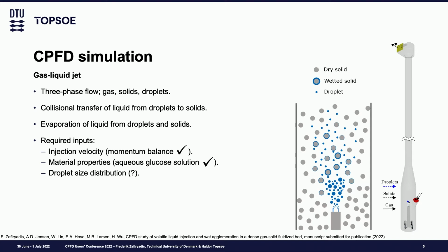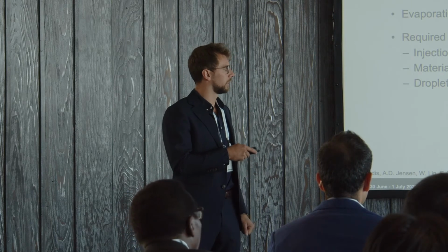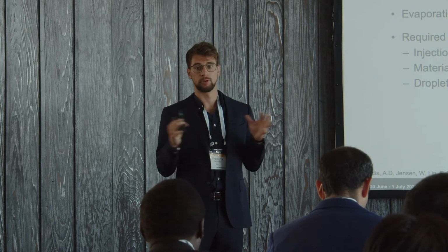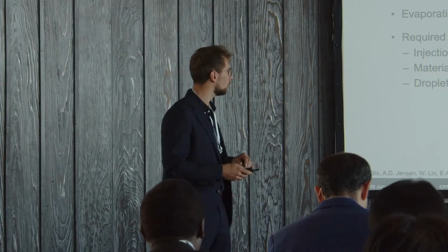The droplets are basically modeled in the same way as the solids. The only difference being that the droplets are allowed to evaporate. And also they can distribute their liquid onto the solid, so you get a thin liquid film from where you can then also evaporate the liquid or crack it. So naturally we would like to optimize this behavior down here so we get the liquid spread to as many particles as possible to get the fastest evaporation and the largest surface area.